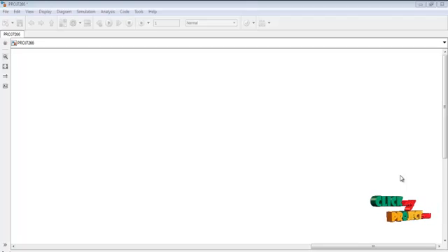In the Simulink library browser, various elements are there. For our circuit, whatever elements we require, we drag them from the library browser to the corresponding model file. After dragging those elements, we arrange the elements as per the circuit in this paper. After connecting the circuit, we click the run icon. After clicking the run icon, the output will be displayed in the corresponding scope in the MATLAB designed circuit.